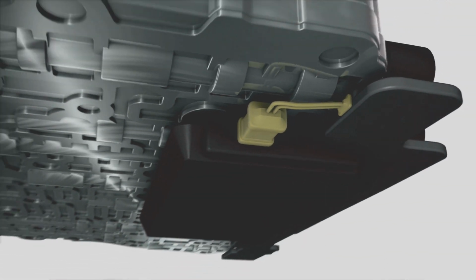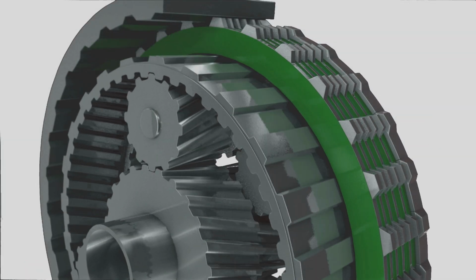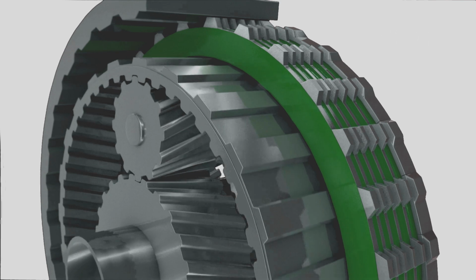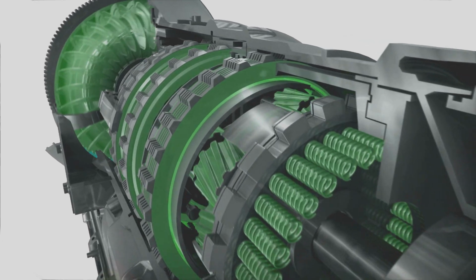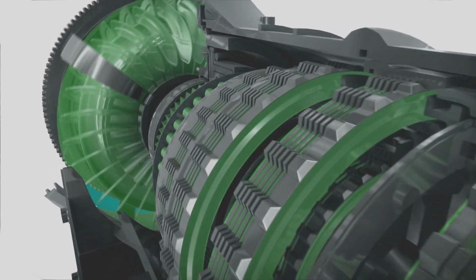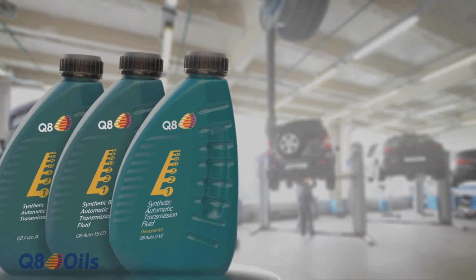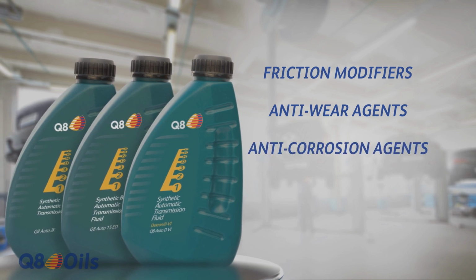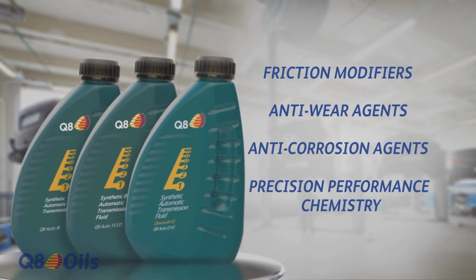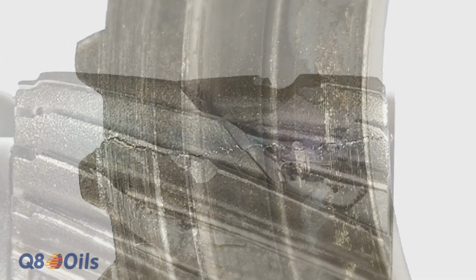And it's got to have low conductivity and be compatible with all electronic components. The ATF precisely controls friction in the clutch packs and maintains it throughout the drain interval, perhaps the most important property of an ATF. And finally, it provides lubrication to the hundreds of moving parts, even under high temperatures and extreme pressures. Modern ATFs include friction modifiers, special agents for anti-wear and anti-corrosion, and chemicals to enhance high heat performance and maintain a specific viscosity. So using the right ATF is critical to the performance and long life of your transmission.